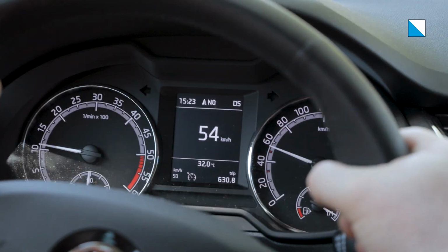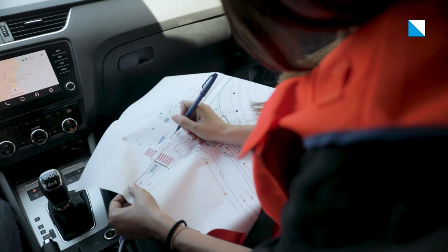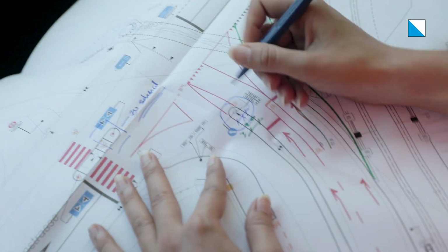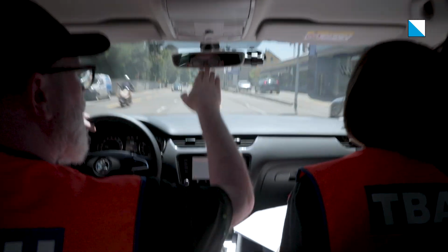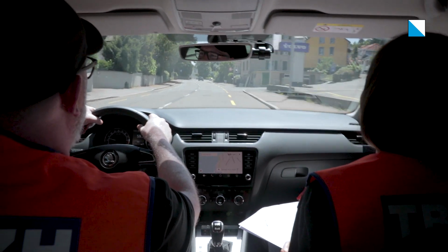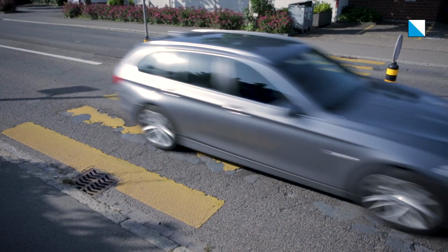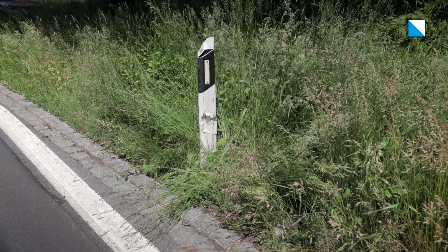When driving with a car, we look for danger spots on the route. This is always done in pairs, a driver and a co-driver. The co-driver can more easily scan the road and search for these danger points. In other words, he notes down all points which do not conform to the standard or which show a considerable accident potential. Along any given section of road, an infinitely large palette and various types of road safety deficits can be found. For example, poor road conditions, overgrown trees or hedges, unrecognizable road signage, or signals that have been run over or are bent.